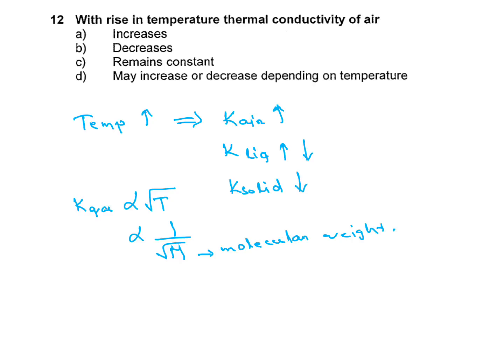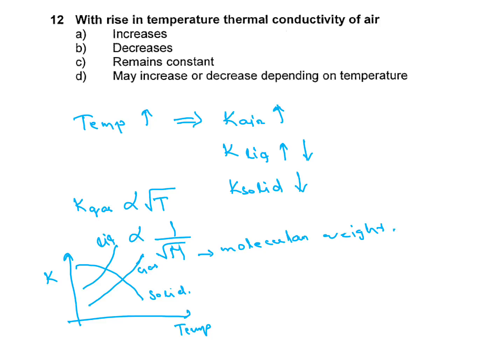And one graph is here. K versus temperature, thermal conductivity versus temperature. This is for solid, this is for gas, this is for most liquids, but sometimes it may decrease. For water the case is different. K and temperature for water.